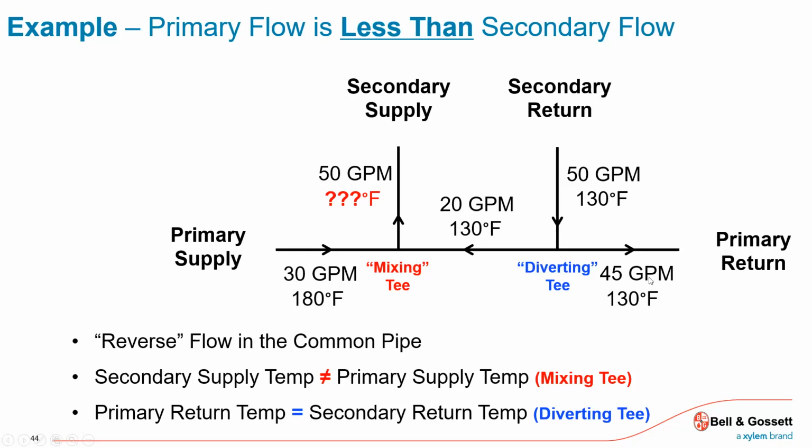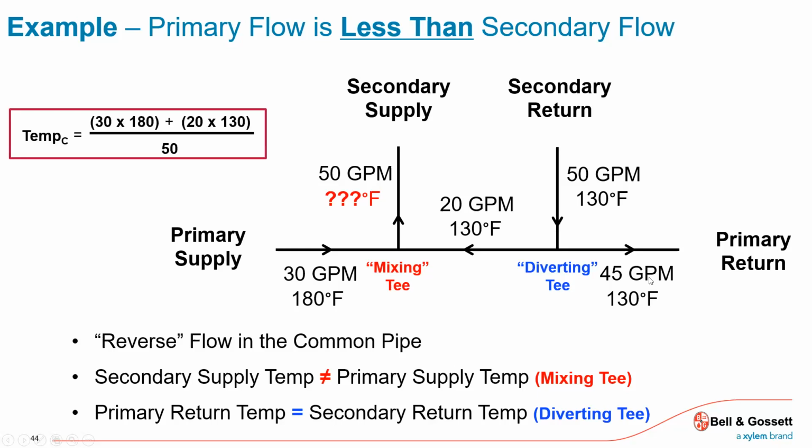So when we say, hey, put in a multiple boiler or put in chillers, 2 or 3 chillers, connect them to the system with their own chiller pumps to my distribution, decouple them with my common pipe. I'm getting all of these features, all these capabilities without having pumps fighting each other. Because that's the concern: you don't want to put pumps right in series with each other, because typically they're not going to be the same size, and that can wreak havoc. One bigger one will really affect, damage a smaller pump.